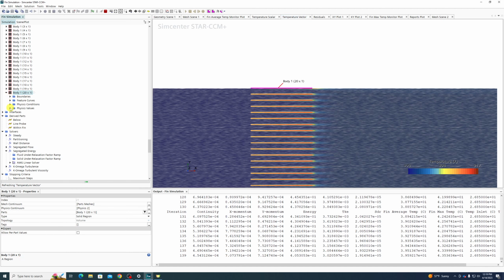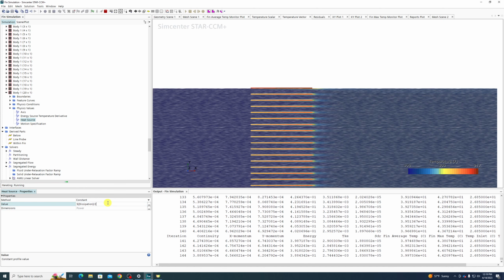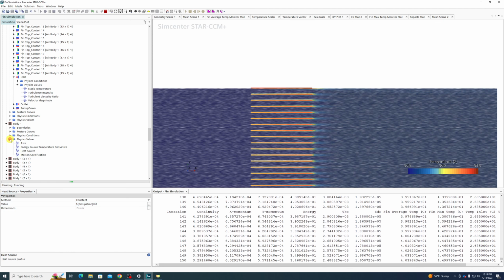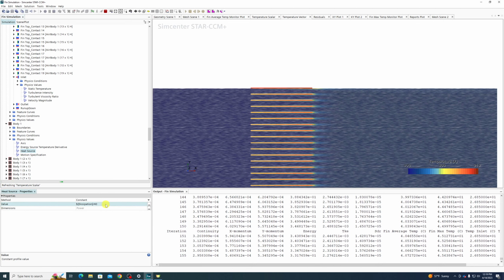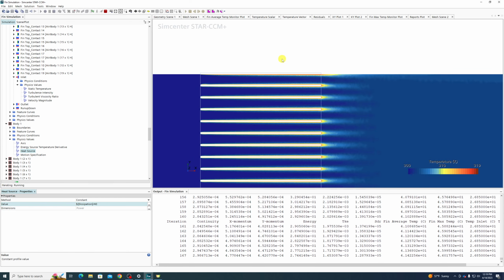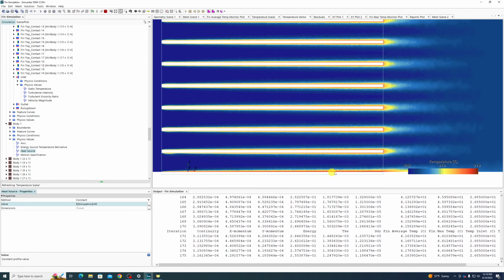So actually what I should probably do is say that this is divided by 40 for the end. And what I should also say is this is divided by 40 for the other end, because technically they only have one side. This other side doesn't allow heat flow through it, so that's going to be problematic. So to keep them all more or less at equal dissipation through each face, we need to effectively have these dissipating half the amount.